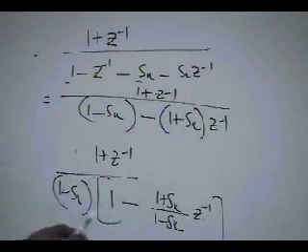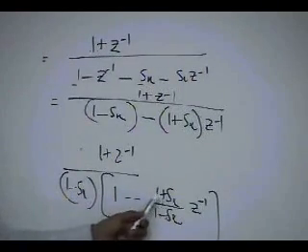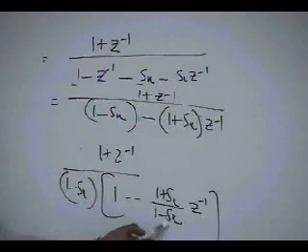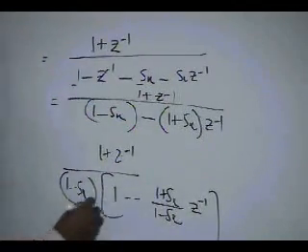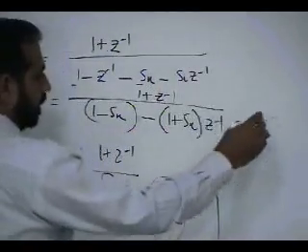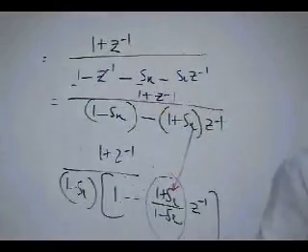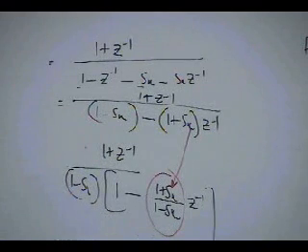As I know s_k is negative, so 1 minus negative will be something smaller, and 1 minus positive will be larger. So this will always be less than 1. So this is the translation. A pole s_k will map into this pole, 1 plus s_k divided by 1 minus s_k, and whatever the scaling and other stuff, but the location of the pole will map like this.